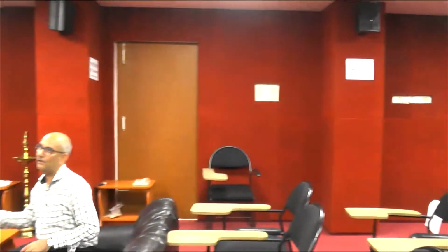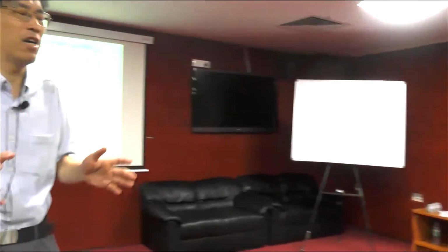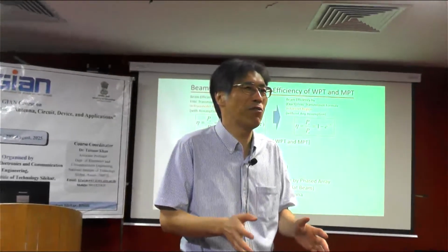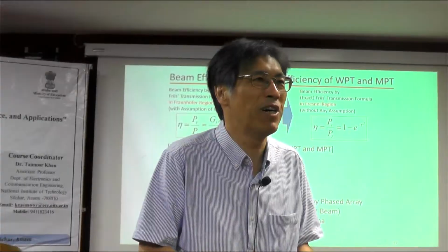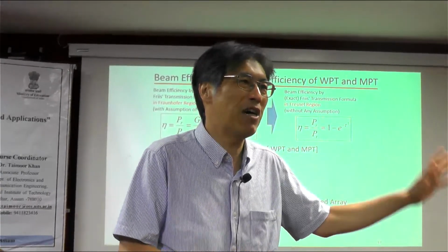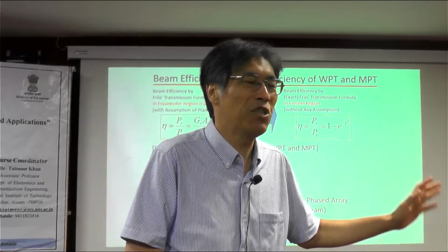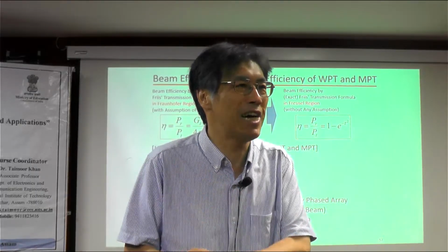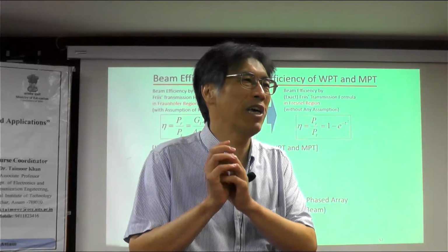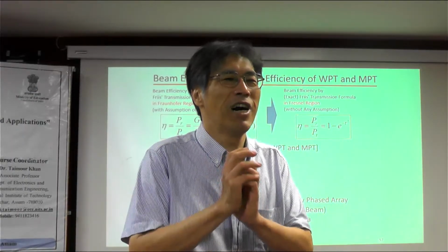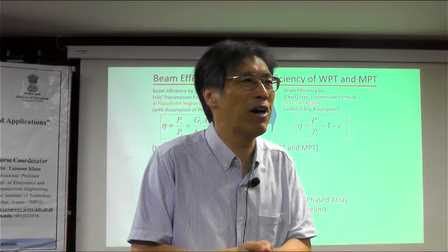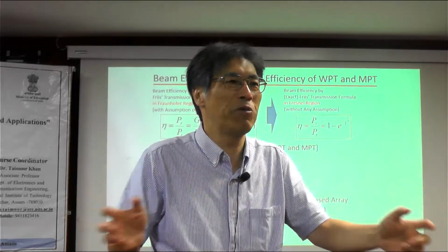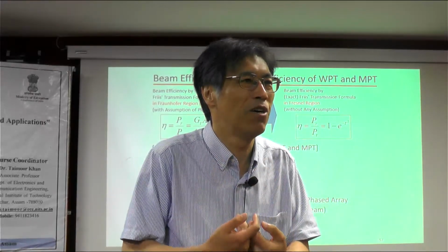Hopefully, the energy harvester is better because we don't need any special transmitter. But there is a big problem with the energy harvester because we cannot control the power density at the receiver. The source is a TV tower or Wi-Fi or others. It means if we need more power to drive the sensor or other devices, and we adopt the energy harvester, unfortunately the only way to increase the received power is to develop a large antenna.